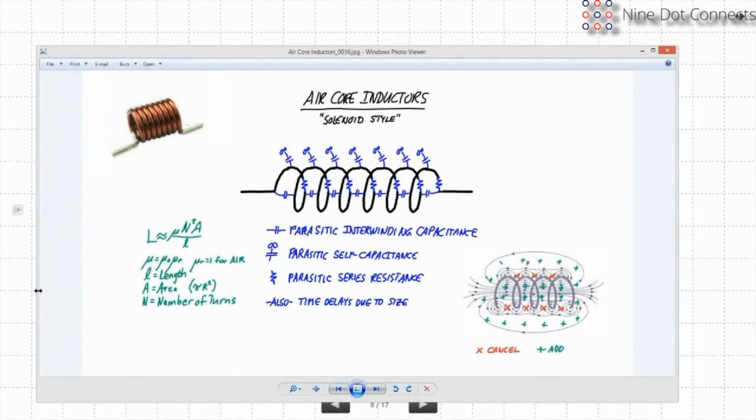As a result, when you get a toroidal-shaped winding, all of the magnetic flux, except for a tiny bit that escapes, stays inside the coil. What that means is that toroidal cores are intrinsically self-shielding. The magnetic field doesn't get out of them. That's very, very important for shielding things. It's especially important at very, very high speeds, and switchers are now getting up to very, very high speeds.